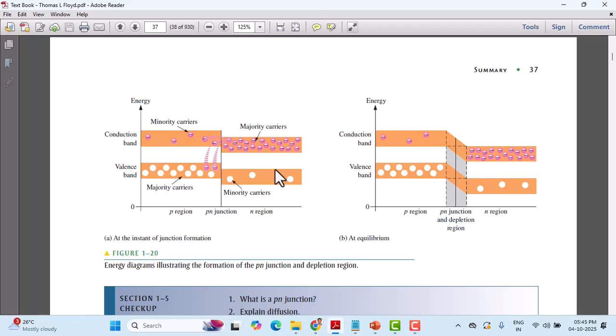So under the diffusion, what happens is these electrons move from the conduction band of the N region, as a diffusion process occurs. They are higher in density. They move from the higher region of concentration to the lower region of concentration. So few electrons may cross, and therefore lose energy and fall into the valence band, as we said already. So now this is what happens under the equilibrium.